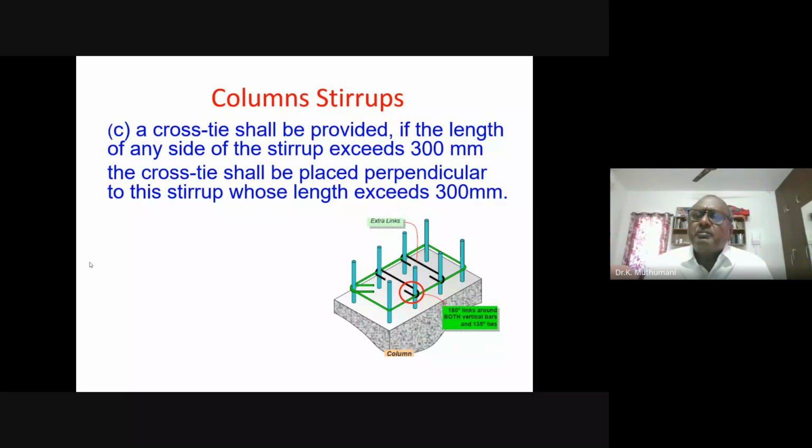It is like working back. You get a reinforcement, and from that reinforcement, find out what is Mu. So the beam capacity on the left plus beam capacity on the right, into 1.4, should be the column capacity. After providing all that, you should check this. If you don't check this, what happens? It may come down and then fail. So that is the important thing. Okay, coming to stirrups, the stirrups are more or less the same as for the beam. But the only thing is, suppose the column exceeds 300 mm, what happens?